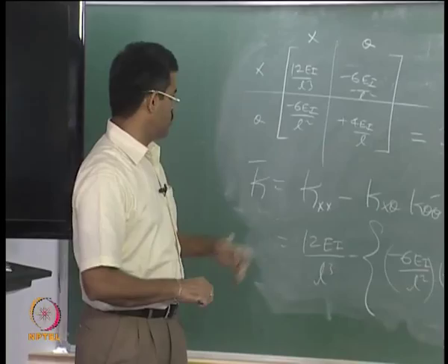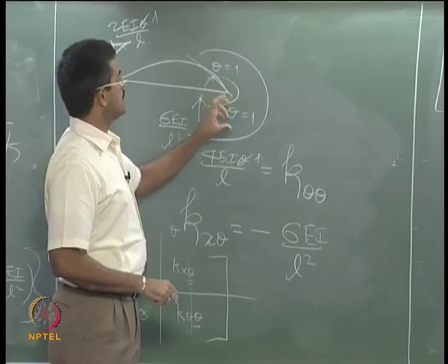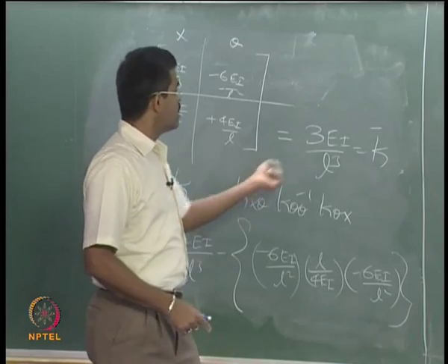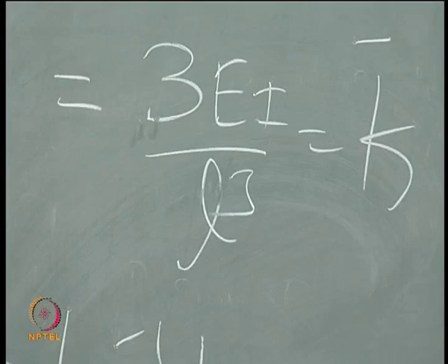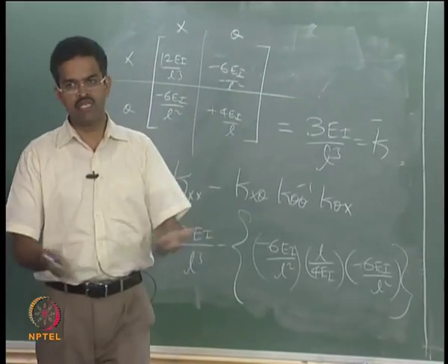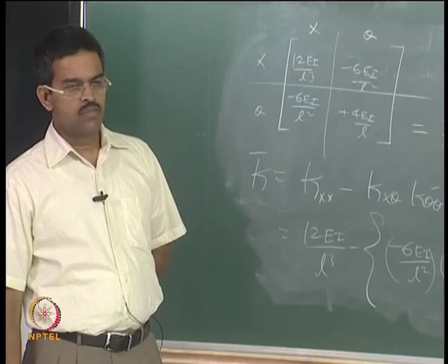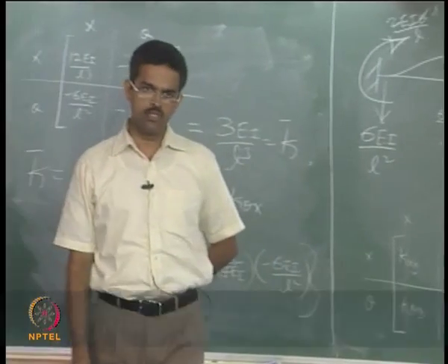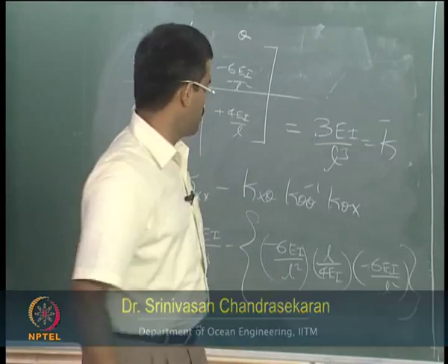Okay, it is exactly the same, but I have used a different technique. Therefore, creating an additional degree of freedom should not cause embarrassment to work out k. Therefore, people still use this number as an equivalent lateral stiffness and solve the problem. I have taken theta into consideration, still I got k bar same as k. I must understand why it is so. I have demonstrated it because of this reason. So, introducing an additional degree should not cause panic in working out k. In that situation, I can use equivalent stiffness, or what I call lateral stiffness matrix, and derive it back again with a simple expression like this.